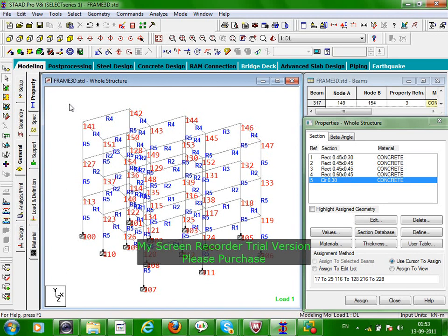So in limit state, what is the limit state concept? If you increase the compression zone concrete, for balancing, it requires some steel in the tension zone. That is your design philosophy of limit state. That's why this is not possible for reinforced concrete. But an optimum solution is possible for steel structure.